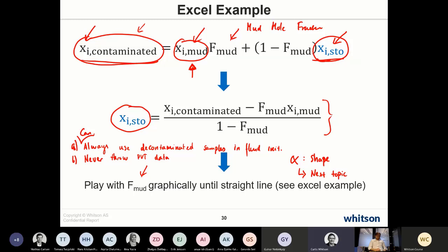Of course, you have to do PVT measurements to get a preliminary equation of state that's definitely better than the predictive equation of state from any of the software. So the answer may be yes, get the data if you don't have any other data. No, don't get the data if you have a lot of the other kind of data. So it's really not a yes or no question.